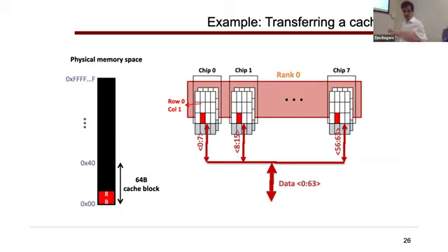And in the same mapping, like I said, we'd light up that row for the cache line. So we're actually lighting up 8 different rows in 8 different chips in 8 different banks, right? But logically the same bank in each chip because this is a big rank. And so then the next 8 bytes would come from the next section and so on. And so if your row was long enough, which they tend to be, then for one cache line, you would have 8 accesses. The first one would take the longest because you'd have to open up the row, and then the subsequent 7 accesses would all be row buffer hits and be able to service them relatively quickly. Okay, if you always knew you wanted a 64-byte quantum from the memory system.